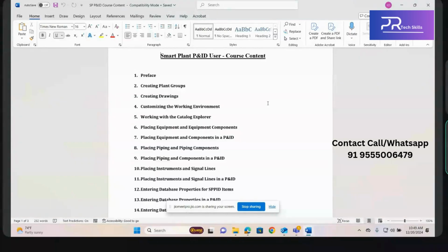Before creation of the P&ID, we create the process flow diagram. We call it PFD. You might have heard of it. It is nothing but a simple block diagram from process A to D. Let's say you want to build one sanitizer plant. Initially, the process engineer creates a process flow diagram.